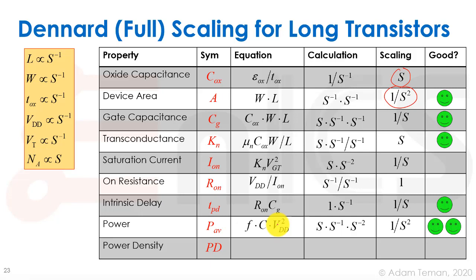So how about power density? That's something we haven't discussed until now, but when we take a transistor and we operate it, the fact that we can put more transistors on the chip means that, even though they have lower energy, the more transistors are going to be making more energy, and that will dissipate more heat. So we actually should look at the amount of energy that we dissipate per size. So that's the power density, or the average power divided by the area of the transistor.